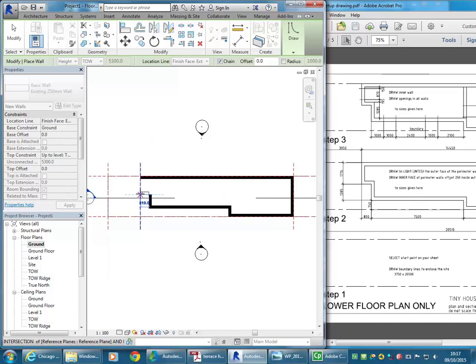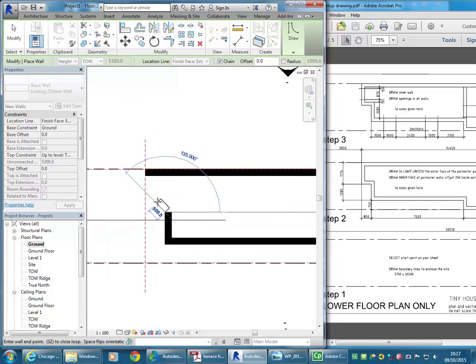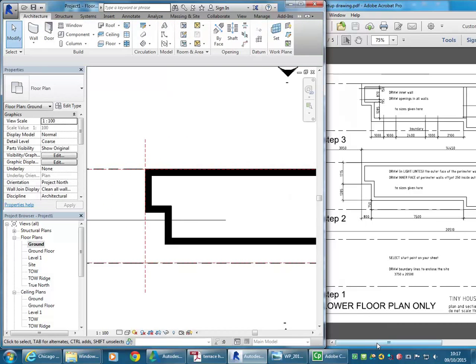And from there on, you should be able to, but you'll see here there's a bit of a mistake. Someone's fudged it a bit in the AutoCAD drawing, because mine's 810 and I don't think my maths is out. So let's see if we can work out where the mistake is. I'm just going to take it across to the reference plane rather than typing in the measurement, which is 800, because we want it to line up with the walls we've drawn. So I've got an extra 10 mil there that's come from somewhere, and then coming up here to the corner, the next one's okay, 1715, so I'm just going to click on that corner there.